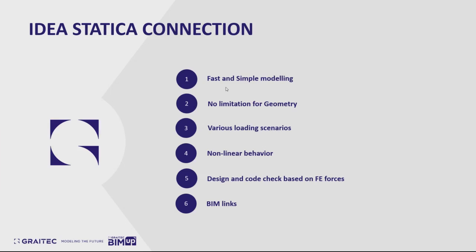And the other part is you can also bring in the geometry of your connection from other software like Advanced Steel or Tekla and others. There's almost no limitation for the geometry of connection. So you can create basically very complicated connections in IDEA StatiCa, but we also have the typical normal connections that you can analyze in IDEA StatiCa.